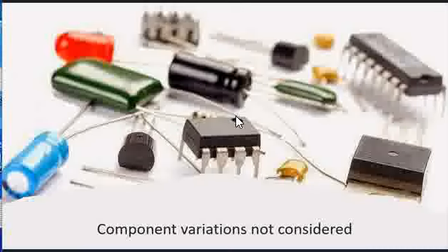So the component variations must be considered by the signal integrity engineer. When a specific series or parallel termination is suggested, it is important that the tolerance of that resistor is also suggested. Mostly the lowest tolerance resistor has to be used in the design, but it is up to the signal integrity engineers to stress that and ensure that it is being used.